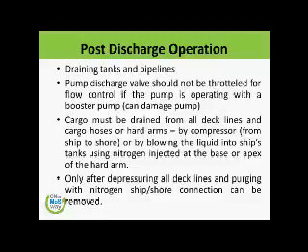And cargo must be drained from all deck lines and cargo hoses and arms by compressor, ship to ship, or by blowing the liquid into ship tanks, etc. And of course, the main thing you need to know is that we retain certain cargo inside the tank.